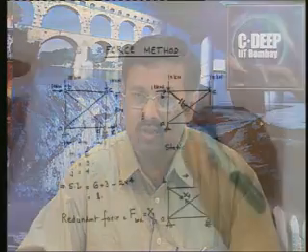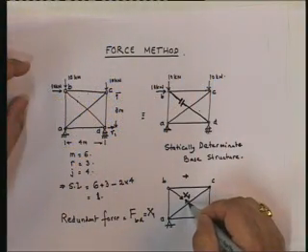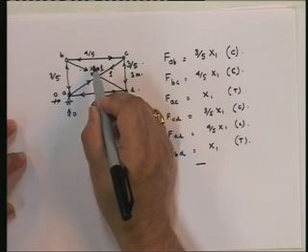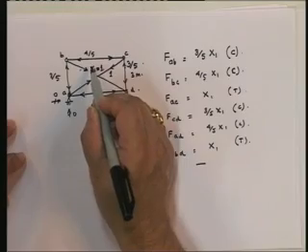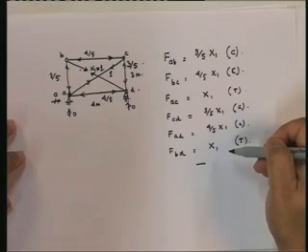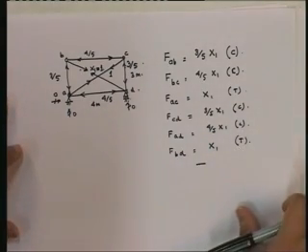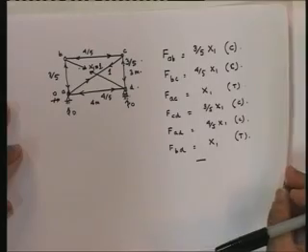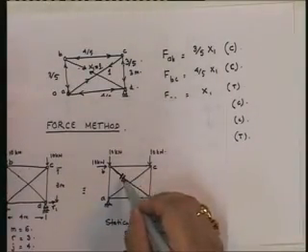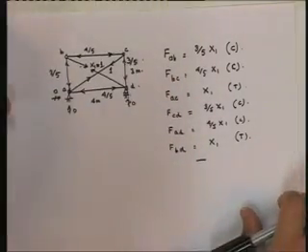Now, what is that force? Note that the force is exactly the same as the redundant force. So when I have actually solved this, I can assume that if I take this to be the virtual force, okay, what will be the forces in all the members? Well, I know what the forces are going to be. I have already got it. Okay, so therefore, if you look at it using the method of virtual force, what is the displacement at this point? The displacement at this point can be given by, I'm going to write down the virtual work equation here.